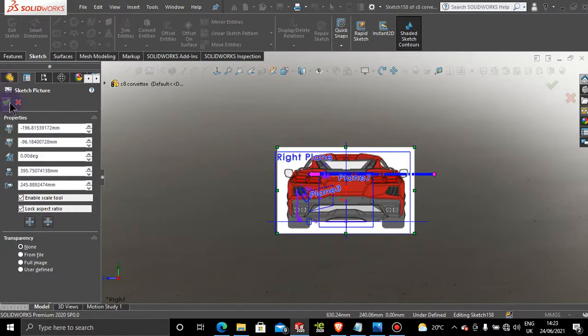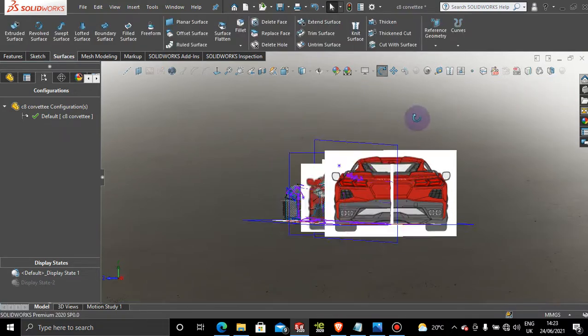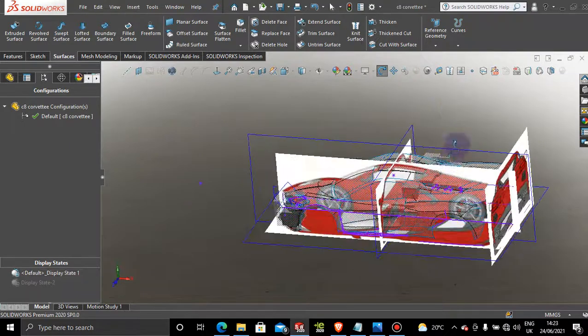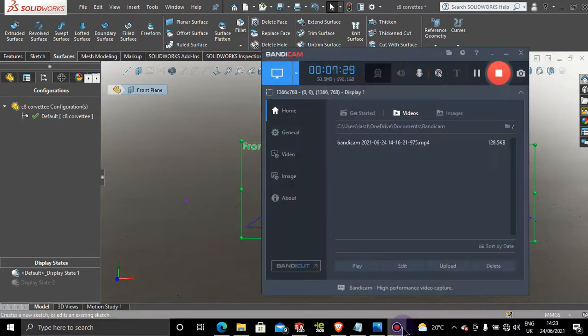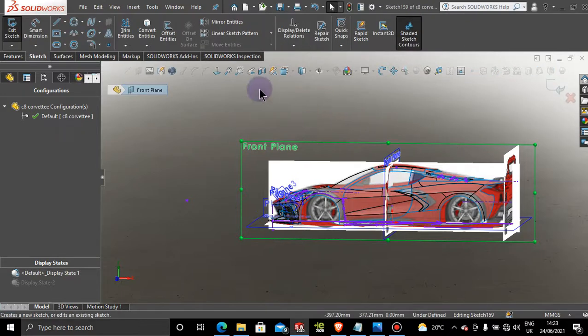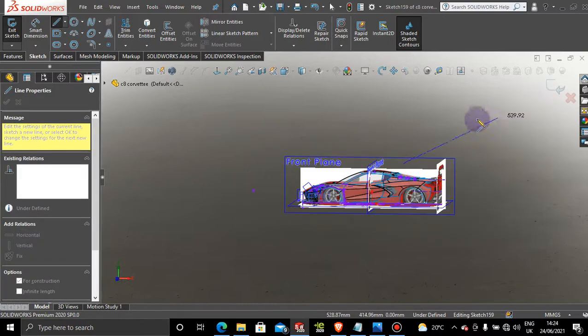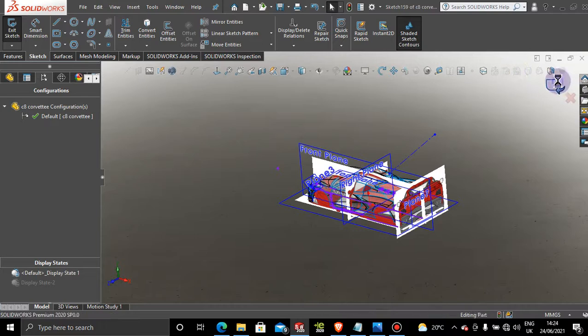and then I'm going to press OK now, because we need to set up some other planes to properly adjust the size of this image. So there's one plane that we're going to add on the front plane here. So I'm going to click on front plane, sketch, and I'm going to add a center line, and that's going to look down from here. It's almost like a camera angle, right? And then we're going to add that plane on this sketch.